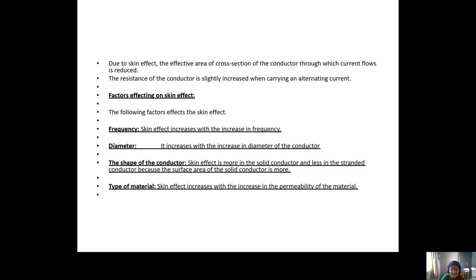It increases with the increase in diameter of the conductor. So the skin effect also increases with the increase in the diameter of the conductor. Next one is the shape of the conductor. Skin effect is more in solid conductors and less in stranded conductors.